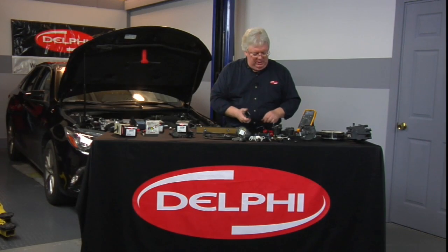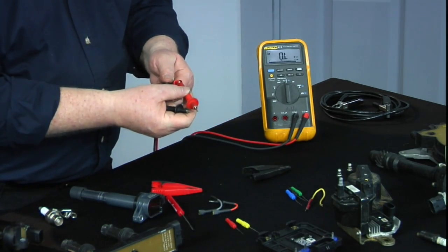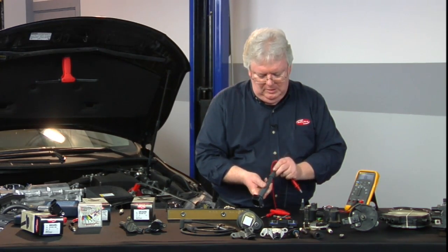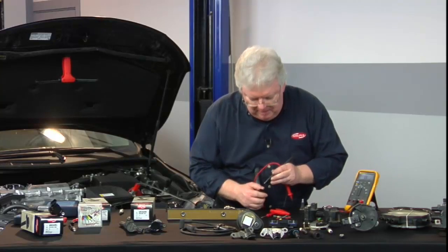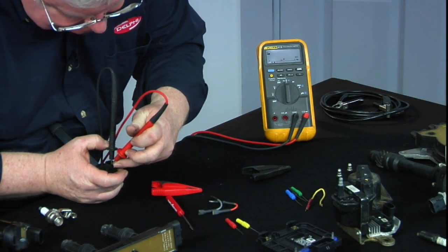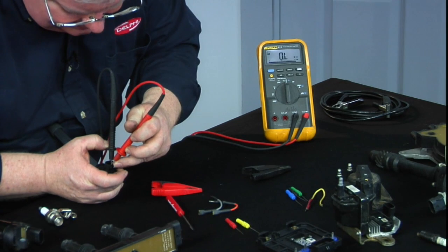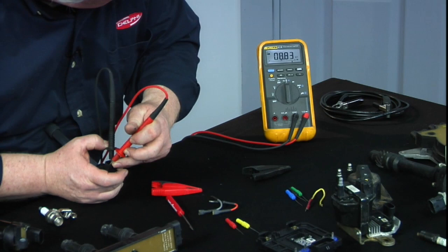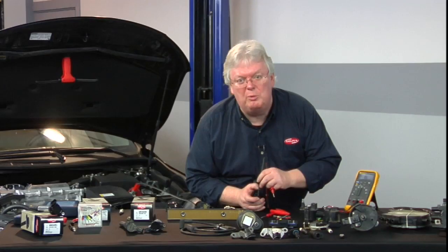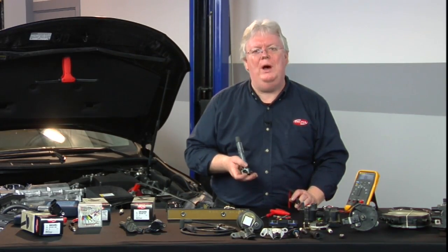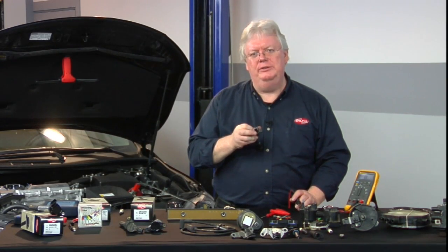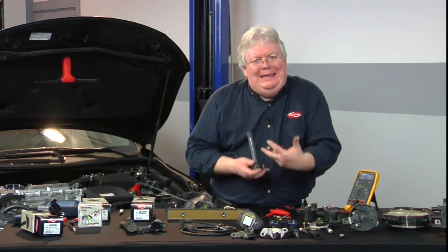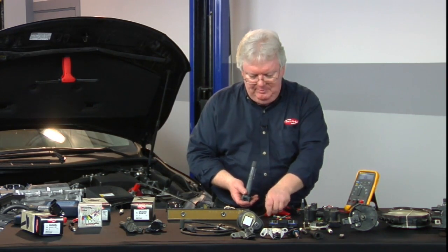Here we have a 3 wire coil. Probes here. And as I measure, let's see here, one terminal to the next, I see some high ohmage, 8 kilo ohms. We're just measuring electronics is all we're doing here. This is a power, ground, and signal wire type of connection. So there's a small module in here, and you're not really measuring a winding at this point. Now, where does the secondary get back into here like it did in these coils? That's going to be a little hard to determine too.